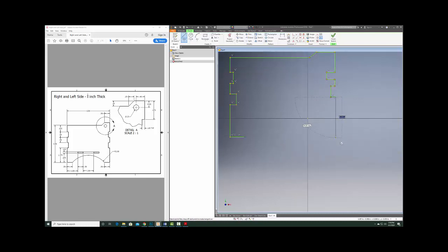Okay, and I'm going to get that lined up, and then I'm going to basically get the shape minus the curve, and I'll just press escape. Let's go ahead and put the curve in. So the curve is an arc. I'll click on the arc tool, and I want to click on this end. I want to get that green dot and also that arrow pointing the red dot. That tells me that I'm right on the end there. And then I'm going to click on the other end, green dot, plus the arrow with the red dot. And then I just kind of make my arc.